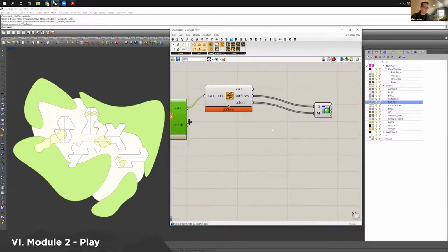That we're previewing. So the way to get around that is by creating a material, and this is a native Grasshopper thing. The reason it's getting blown out is because the default preview, the way it creates materials to preview, is they're super shiny. And this command makes it so that they're really not shiny at all.